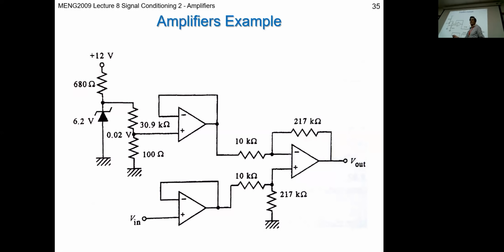So this gives us our nice high input impedance, which was specified in our question. But the voltage output is the same as the voltage input because it's a gain of 1. There's no gain on that. So now we go through our inputs here. We've got our ratio, so we're going to have our V out equals V in times 21.7, our gain.